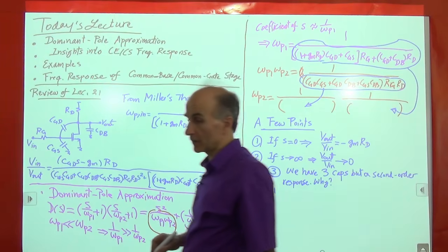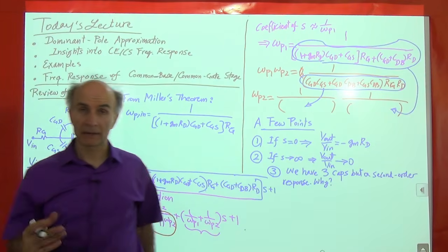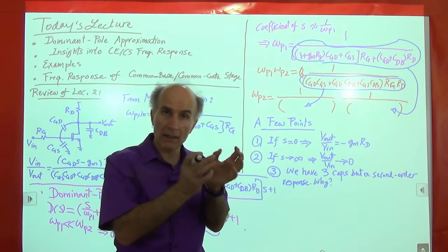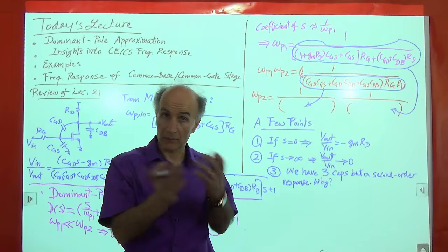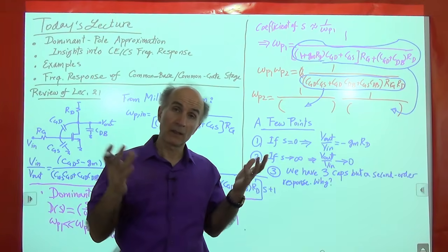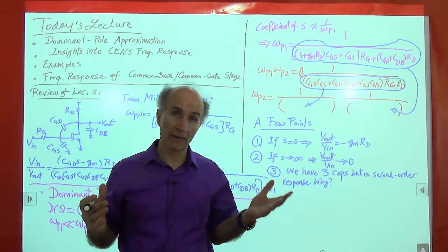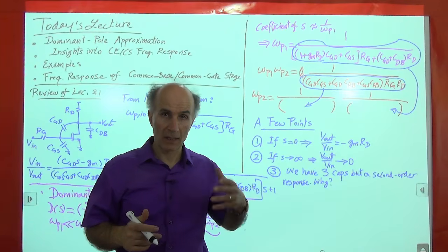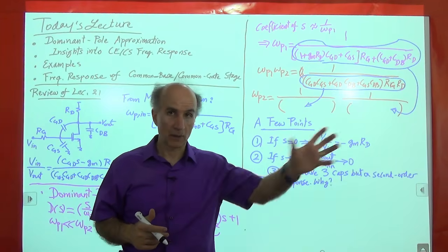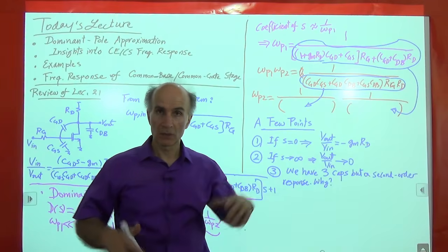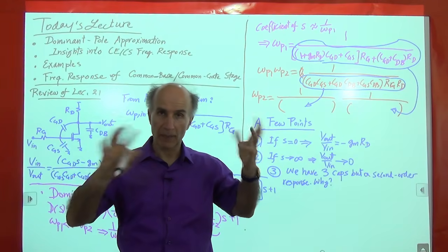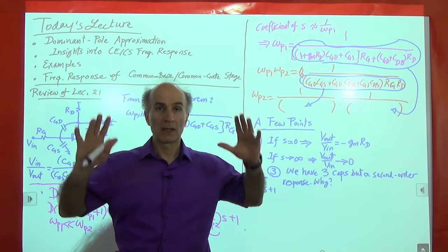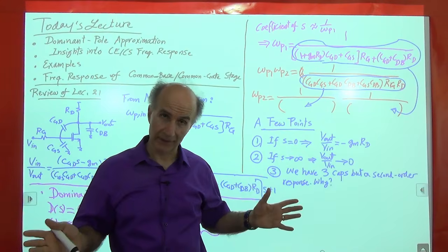Now, in basic circuit theory, you might have had this concept that if a circuit contains n capacitors and none of them are in series or parallel, then the final transfer function should have an nth order, right? And more generally, if you have n storage devices, some capacitors, some inductors, the total number is n, and again, no parallel or series combinations between the capacitors or between the inductors, then the order of the system should be n.